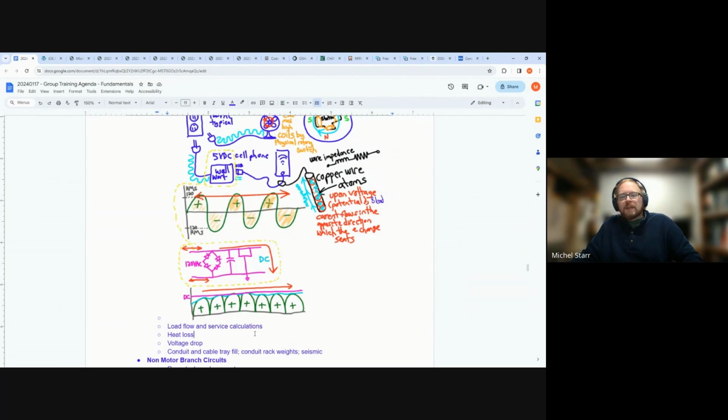So we would maybe give it in watts. Like a panel board, a whole 42-circuit panel board might give off like 200 or 400 watts of heat. And I mean, the heat loss conversation is the watt loss, heat loss, heat gain. If you're the HVAC engineer, you might consider this heat gain because there's heat gaining in that room, but just try and put them in perspective.